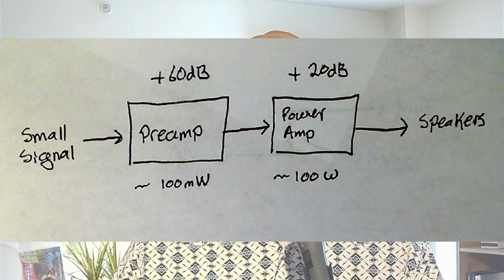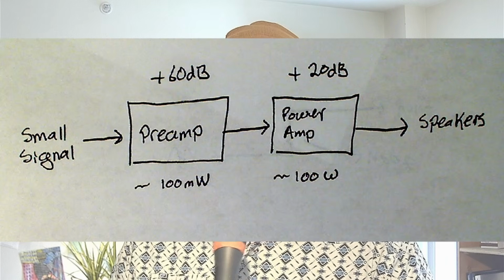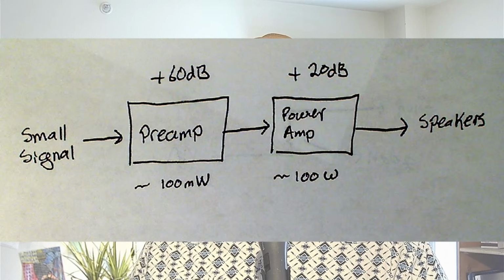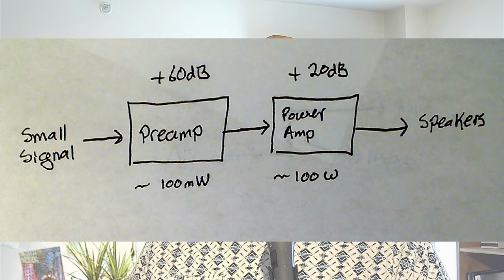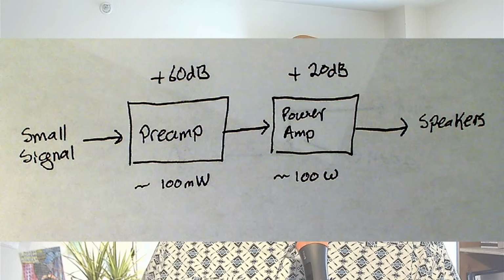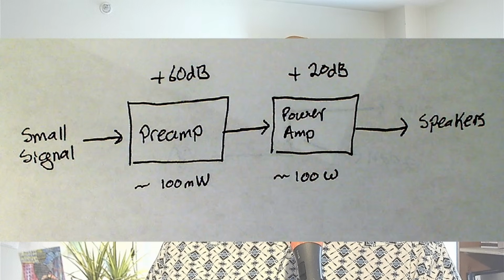Next type of circuit is audio circuits. Now, this one is actually a subset of power electronics. If you consider a power amplifier, it's going to take a small audio signal and convert it to a big audio signal. It's going to convert something that is line level, or maybe even smaller, microphone level, and convert that to speaker level. It's going to boost it by several tens of decibels. And ideally, it's going to do so cleanly because you're going to listen to it.